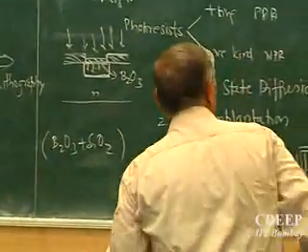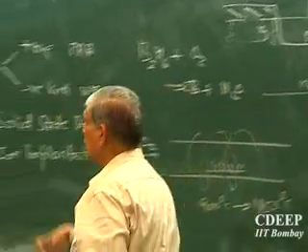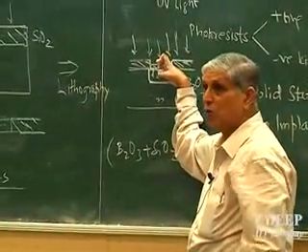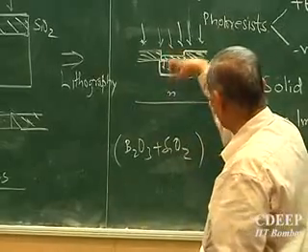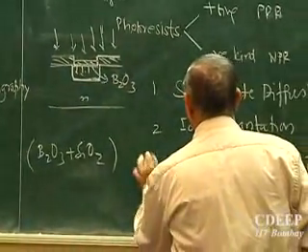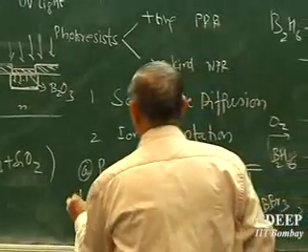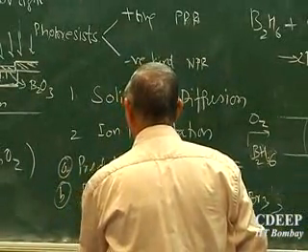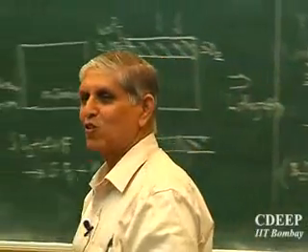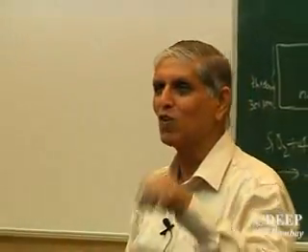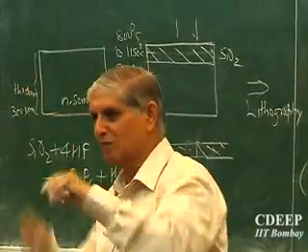Now how much deeper you want? This is called junction depth. And how deep you want will be decided by how much boron glass you initially create, at what temperature you create it, how much boron content it will have, and how long you let this impurity diffuse down. The first process, as I said, I called pre-deposition, in which oxygen was present. Next time, no oxygen. The other is called, and this word is very interesting, drive-in. Impurities are driven in. Someone years ago even wrote 'driving' in an exam paper. I said, I'm not driving a car, but because I keep saying drive-in, people thought I'm driving something.